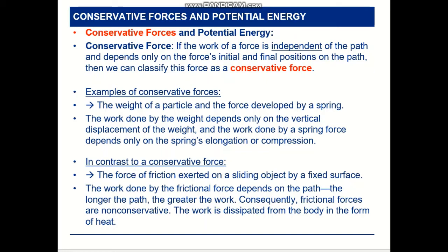An example of a conservative force is the weight of a particle and the force developed by a spring. The work done by the weight depends only on the vertical displacement of the weight, and the work done by a spring force depends only on the spring's elongation or compression.